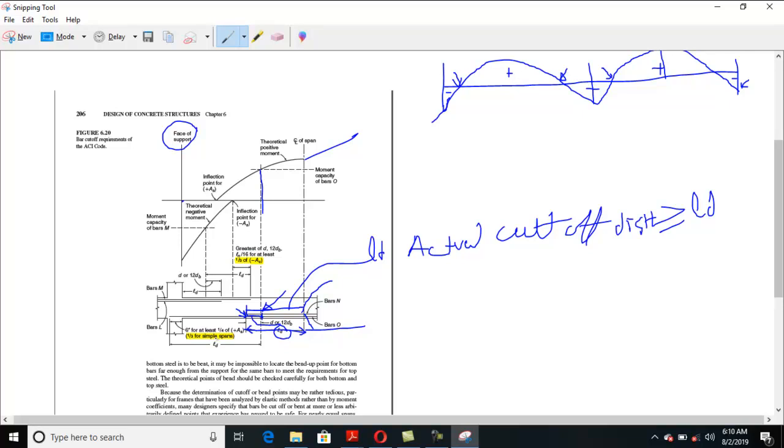And the steel area which you cut there, the continuing area, the rest of the bar area, must be equal to or greater than 1/4 of the total positive area. Clear? And those bars must be extended into a support for a distance of 6 inch. Clear? For a simple span, I already mentioned, the continuing area is 1/3.